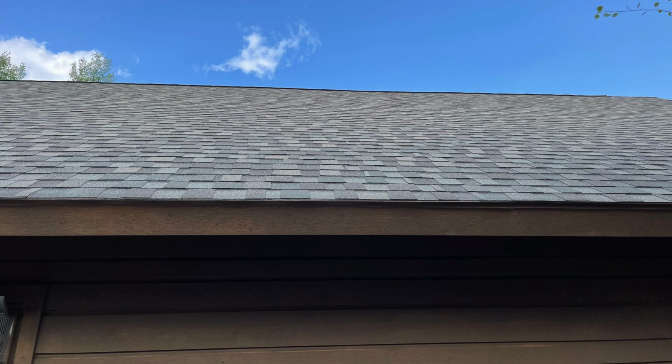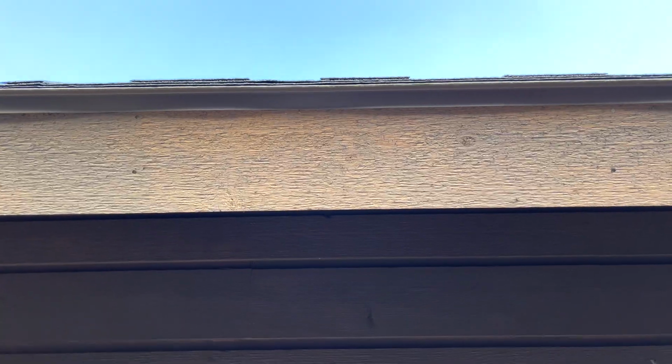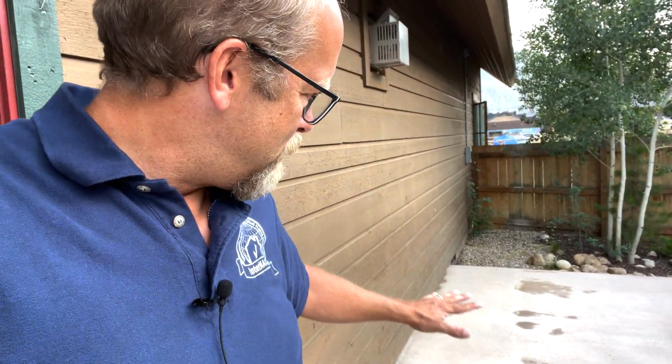And it's common practice up in the mountains to not have gutters. It's funny about code in some areas. Gutters may be required, for sure. It's fairly common in the United States and North America to have gutters, but in certain situations, gutters are not required, like this house. Now, because there aren't any gutters, I'm gonna take a look around the surrounding areas and the grading. And where I see a hard surface, we want a nice slope to grade away, to drain away, to divert away that water that falls off this roof without any gutter catching it.